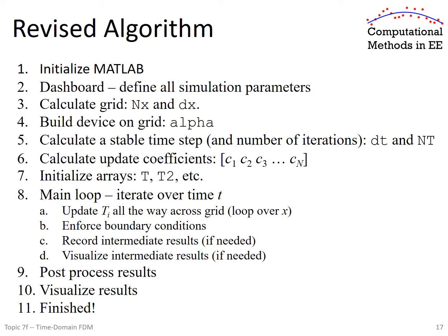Well, after the time loop is over, the simulation really is over, and we recorded some things probably. Now we can post-process them to learn something. Maybe we visualize the results. Maybe we've been rendering a movie, and we have this movie of temperature as a function of time. But that's it. And really all time domain finite difference methods follow a very similar flow. They'll just have different numbers they're calculating, different update coefficients, but they all really have the same flow to them.